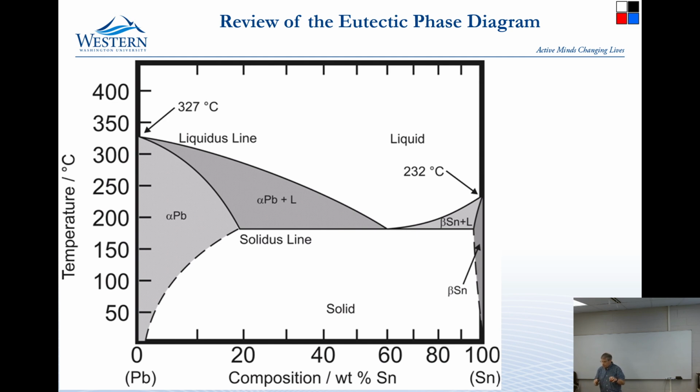Little globs will just appear in the solid. They are getting there by diffusion. They are moving within the crystalline lattice structure, because they're smaller than the lead bits, and diffusing into little globs. And thermodynamics drives this, that they want to separate and become little globs.